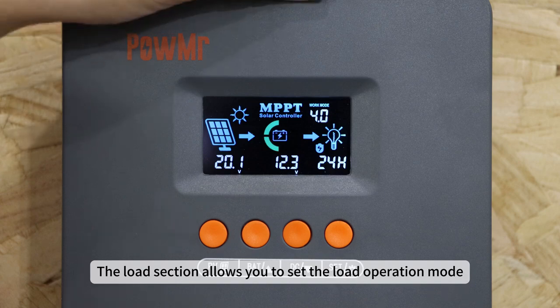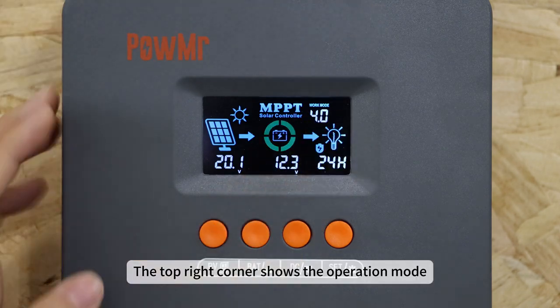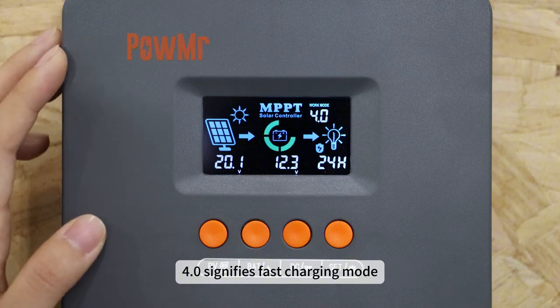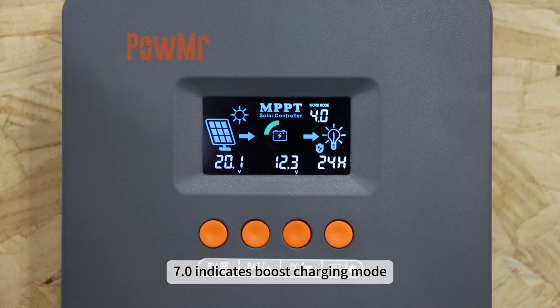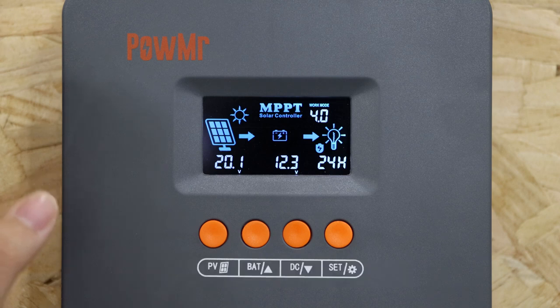The load section allows you to set the load operation mode. The top right corner shows the operation mode. 3.0 indicates night mode with no charging. 4.0 signifies fast charging mode. 7.0 indicates boost charging mode. And 8.0 represents float charging mode.